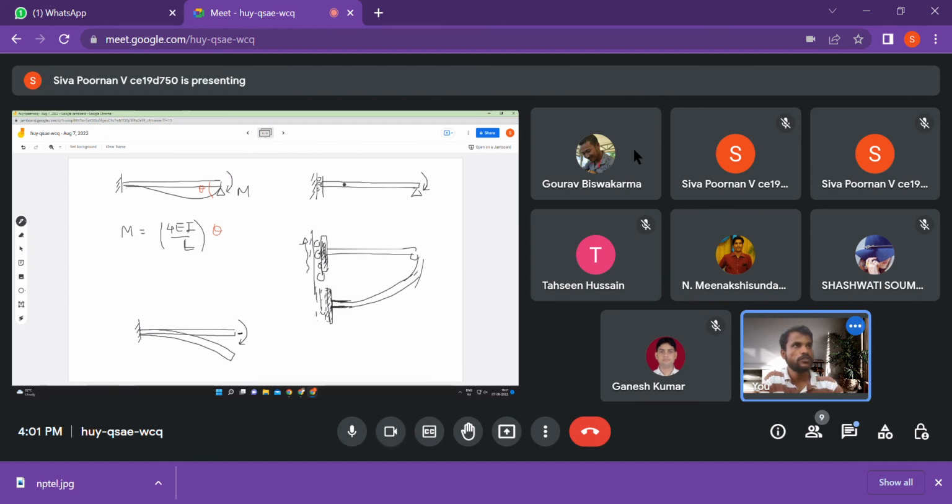So the answer to this is that we cannot have a deflection at this point, but if you see, the bending moment will be the same for these two. So what will happen is that it will deflect like this. It should also hog because the bending moment will also be the same. You can try to find it out because it's a determinate beam. You will see that it is also hogging. The only way it can hog is if this point moves up, because this point cannot move.